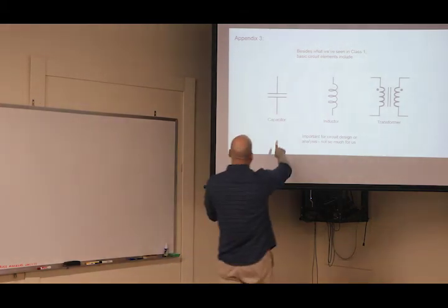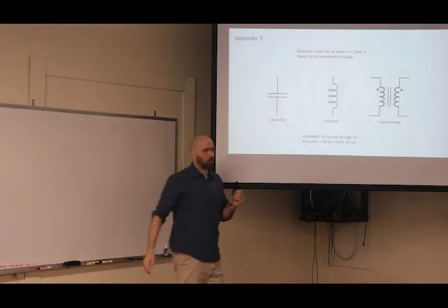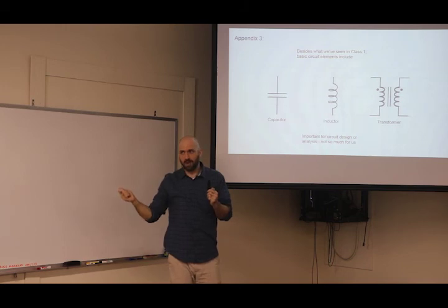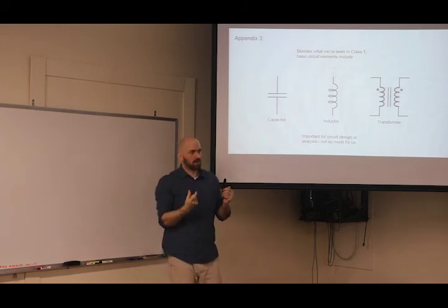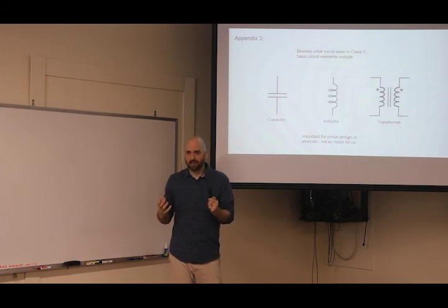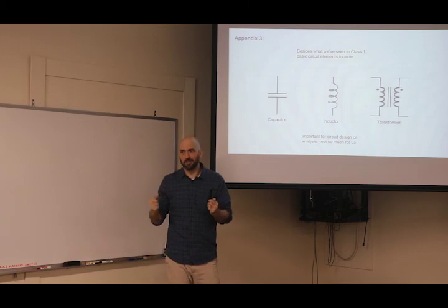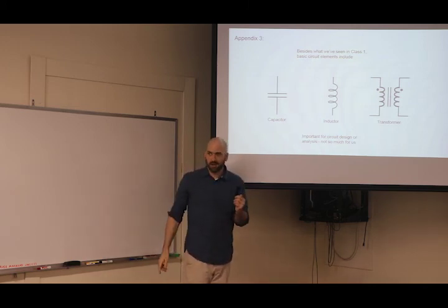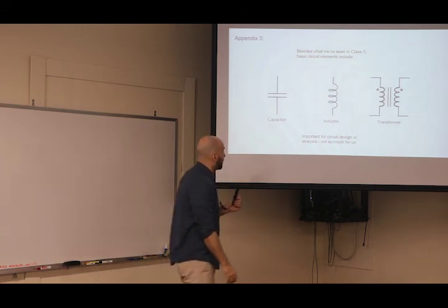I guess the only thing to be wary of is that capacitors hold charge. If I put 9 volts on a capacitor and then take the 9-volt battery away, that thing is going to be holding a 9-volt charge. And unlike a battery, it doesn't need a chemical reaction to take place to produce charge. It's just 9 volts sitting there ready to go. So people can be injured, or you can really screw up electronics, if you're discharging that where it shouldn't be.